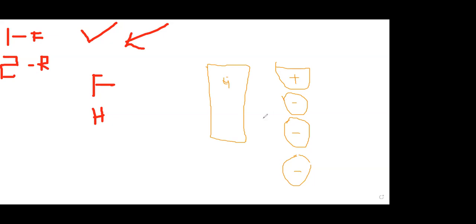So let's say that this first block is forward, and this one is reverse. Now, if I press the forward button, it is showing forward, not a problem. If I only have the forward coding, when I press the forward button, it shows forward. But when I add the reverse coding and press the forward button, it is switching between forward and halted.